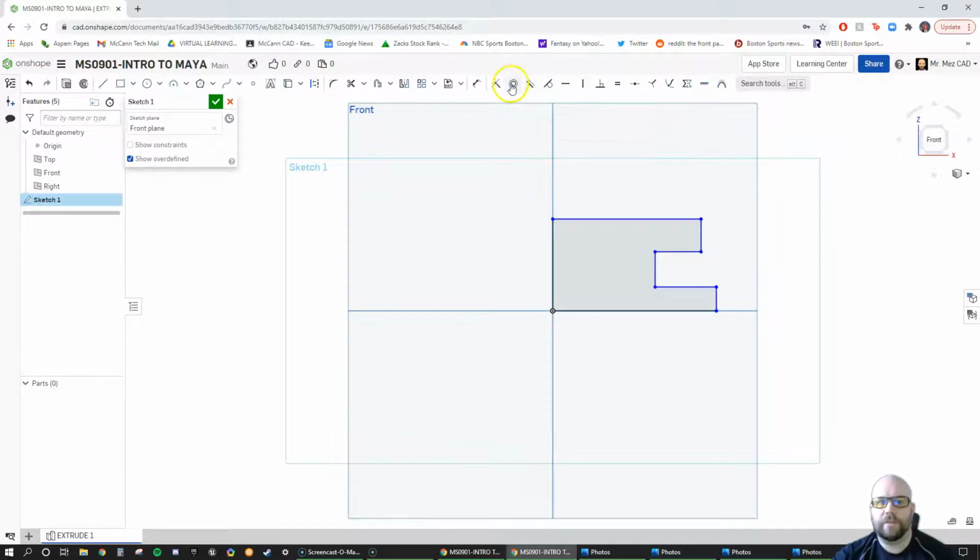All right, so this section right here, where we have coincident, concentric, parallel, tangent, horizontal, vertical, perpendicular, equal, and midpoint. These are called constraints. Constraints are the first place you should go when you're modeling, okay? So I'm gonna click on this vertical constraint, and I'm gonna pick this point, and I'm gonna pick this point. And now it's gonna move those over to say, these are vertically in line with each other, okay? Which means if this line moves, this one up here, then this line's gonna move as well.